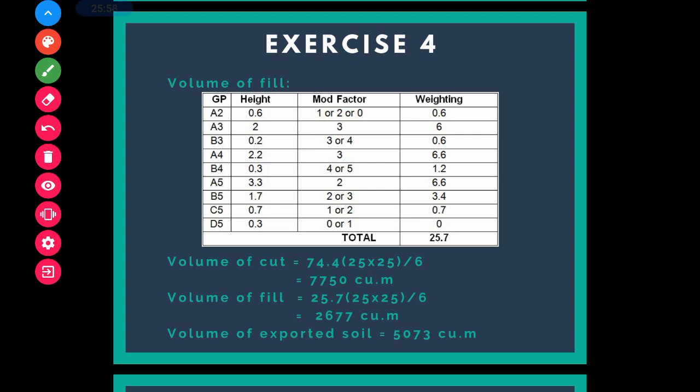Then based on the question, the student needs to determine the volume of imported or exported soil, if any. Based on our calculation, the volume of cut is more than the volume of fill, meaning that you have an excess volume of soil, so you can sell the excess soil, meaning you have a volume of exported soil.